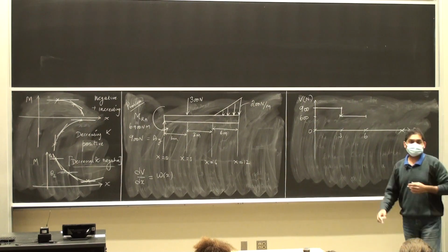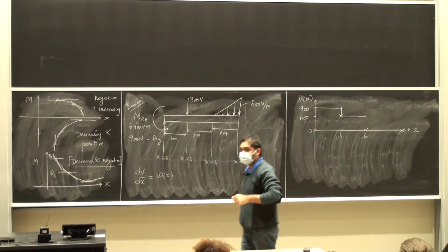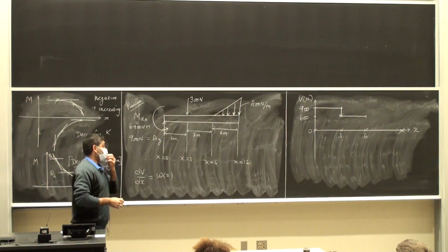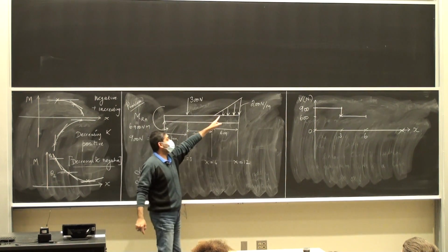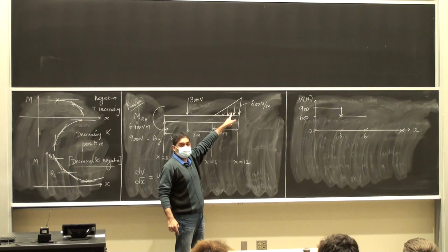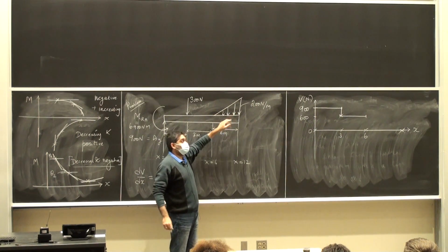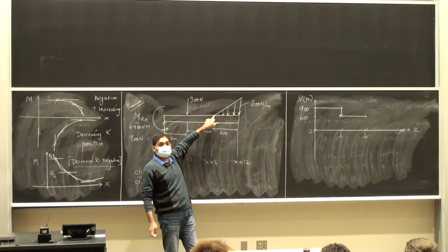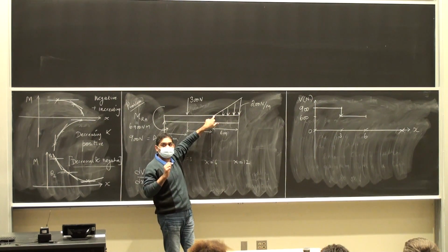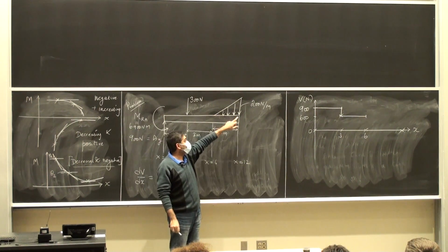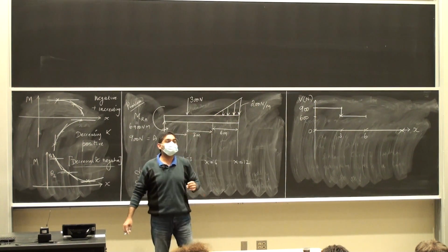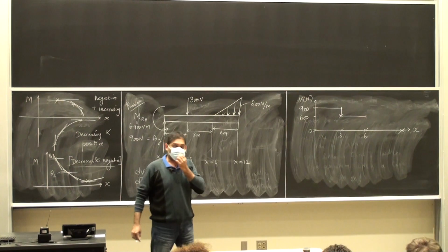How do I go home? Yes? Negative increasing. Fantastic. So the slope is negative because the intensity is pointing down, and it is increasing in magnitude because I'm starting at a 0 slope. Look at this. Starting at a 0 slope here, and then increasing all the way to a slope of 200 newtons per meter. Okay, so 0.